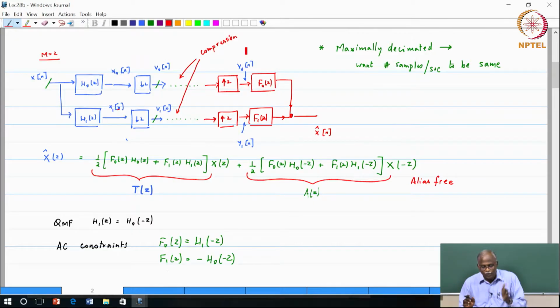So how do you test whether your recombining section is working properly? The way you do that is, assume that there is no compression. Can you recover the original signal? Exactly. If you can, then your reconstruction part is working fine. You kind of have to test it under the case of no compression, but if you are not going to do any compression, then there is really no reason to split it and then recombine it. The whole reason is you are splitting for a very specific purpose like compression or storage, and then at some point you will want to recover and retrieve the signals.